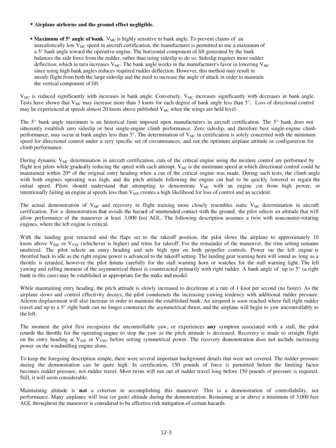The 5 degrees bank does not inherently establish zero sideslip or best single engine climb performance. Zero sideslip, and therefore best single engine climb performance, may occur at bank angles less than 5 degrees. The determination of VMC in certification is solely concerned with the minimum speed for directional control under a very specific set of circumstances, and not the optimum airplane attitude or configuration for climb performance.